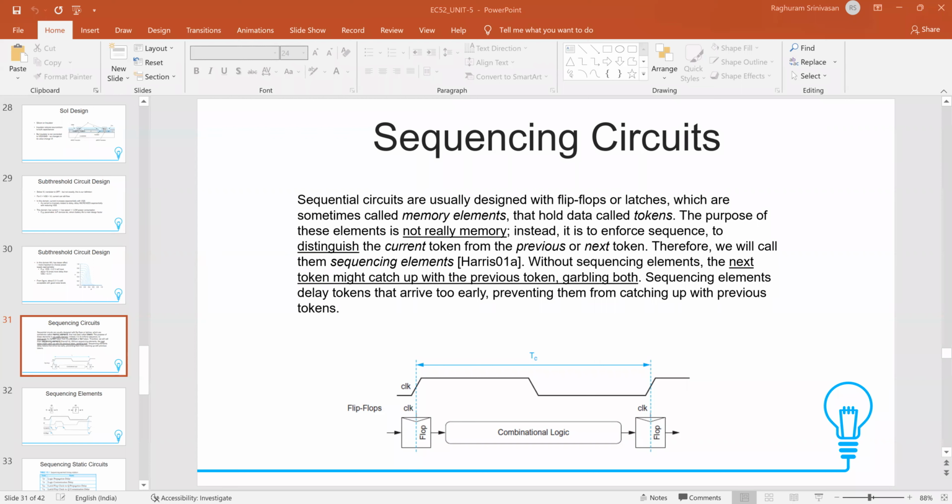So physical design, your teachers also might have talked to you. It's all about designing the circuit so that all the timing constraints are satisfied. There are other constraints, power, area, etc., but those are very difficult to reduce from a layout perspective. From a layout perspective, the only thing that you can do as a physical design engineer is to add buffers or try to modify the floor plan, etc., in order to improve the timing constraints. So what are the timing constraints? What is the meaning of setup time, hold time, etc.? All those things we will see in this particular topic.